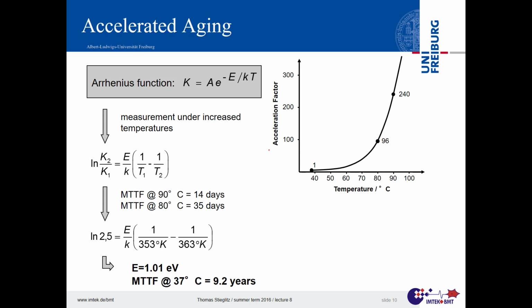So it must be still according to that equation. If we are in those boundary conditions, and in polymers less than 60 degrees C is a kind of rule of thumb. We should not go above 60 degrees C in polymers. In semiconductor materials or ceramics or metals, we can go up to 90. Above 90, it's a bit critical, since we do not want to have our water being boiled.